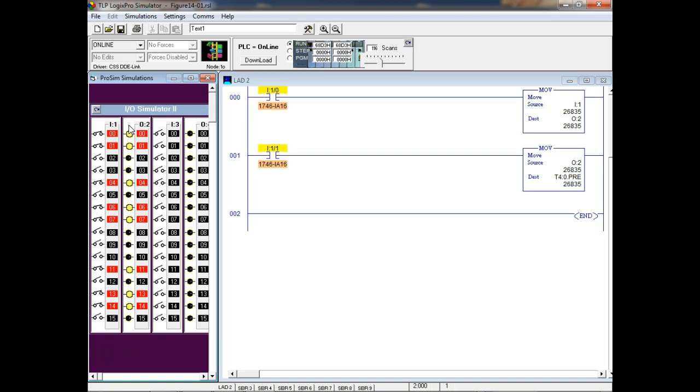Where it says the destination, can you go down to bit level? You only go to the word. No, not with the move instruction. Your add instructions and your move instructions deal with words. Now we can strip off sections of it by using what we call a move with mask, which strips off what we don't want, and we'll look at that in a second.